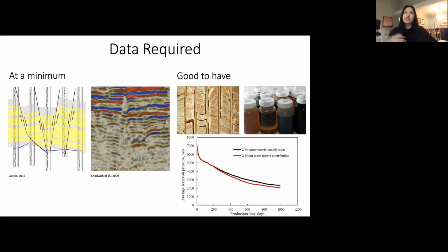And as I mentioned, there are many options to store CO2. If you're doing CO2 storage for the CO2 EOR purpose, you will really need pressure data, especially if the field is running. It will help you set up the simulation and the injectivity so that it won't reach overpressure. In a CO2 EOR, it will also let you know when to inject the CO2, and when to inject water to drive the CO2 that is miscible with the oil.